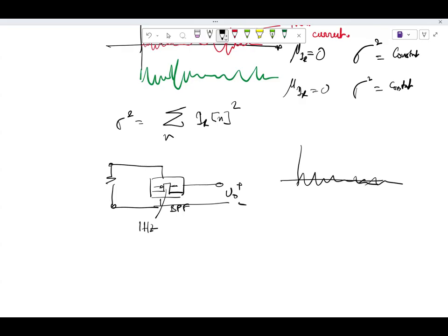So this voltage will have some fluctuations. When I'm saying power, what am I doing? I'm basically saying that if this is V(t), there is a fictitious resistor R across which this voltage has been applied, and I am doing 1 over T, integrated over T from 0 to infinity, with the limiting value of T tending to infinity. This is the definition of power, correct?